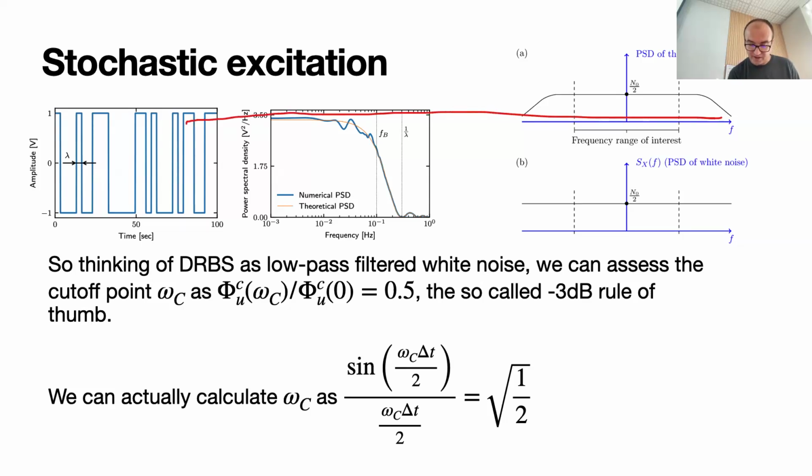But if we make a low pass filter here, we are actually generating a noise-like signal that is a white noise filtered out. And when we filter it out, we remove a large amount of energy, plus to minus infinity, and we have a finite energy signal. This means that we can generate this quite easily.